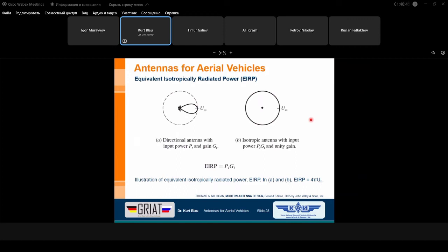And this is the problem, not the receiving power. If you could switch the antenna to act only as a receiving antenna, then it's allowed. Then you can use an antenna with a much higher gain, but you have to ensure that the antenna with this high gain can never act as a transmit antenna. And this is not so easy to realize in practice.